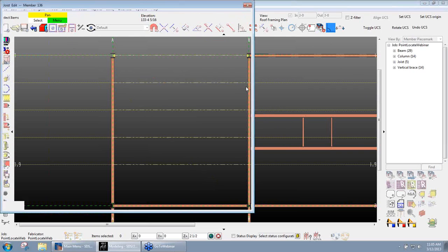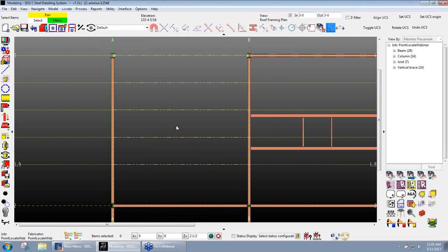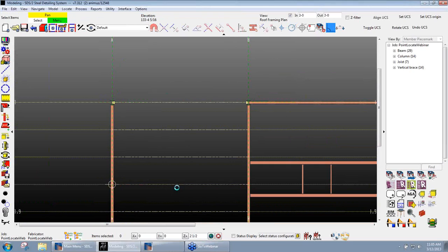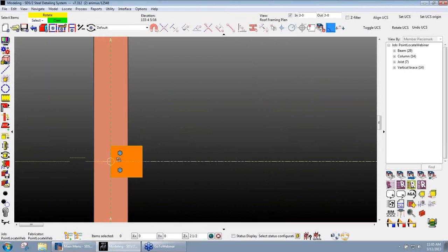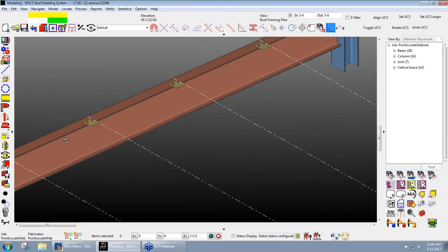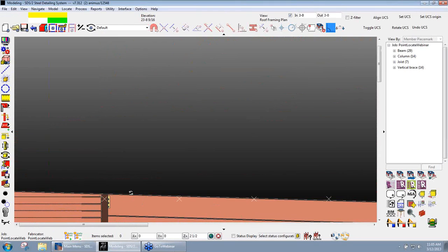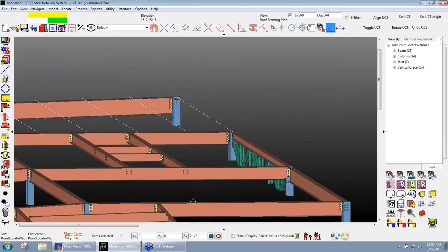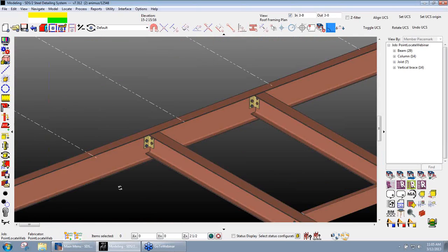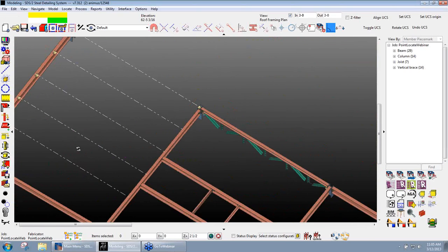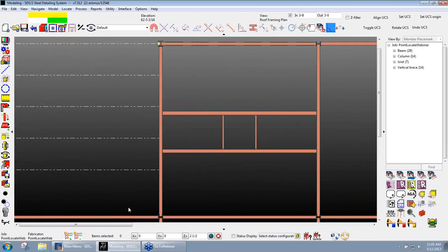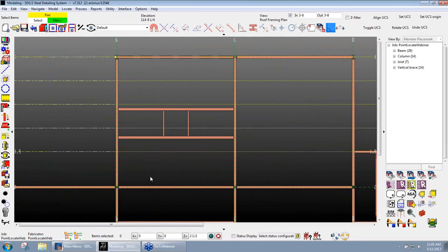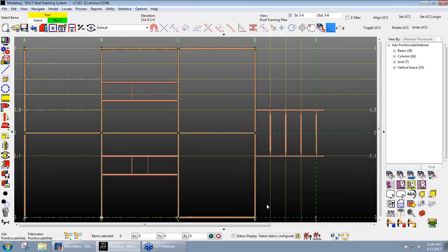So it makes it easy. I just put in that 2.5, and then I don't have to adjust all my elevations, because each one of those would be at a different elevation. So if I look here, I think I snapped to the wrong intersection point there, which is why they're down a little bit. But we can kind of get the idea what that Z offset does for us, where it offsets the point that we're actually picking there.